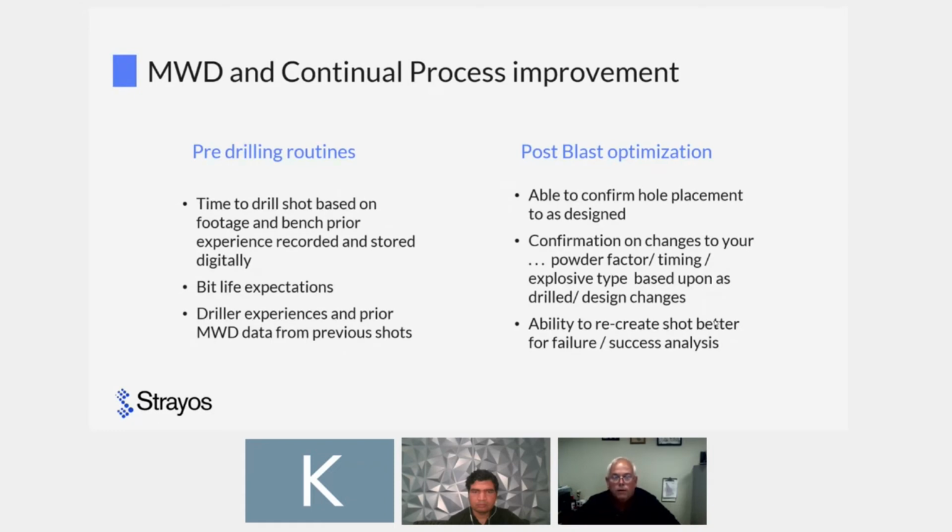What changed? And post-blast optimization, able to confirm hole placement as designed. That is a big deal. It does change with your hole placement how the shot goes off. And if you can actually confirm that we drilled it as designed, or no, we didn't really actually hit the holes that needed to be hit where they needed to be on target.